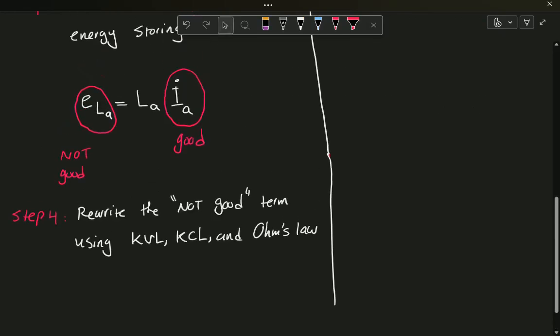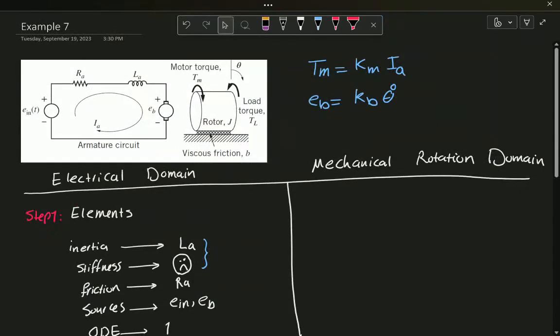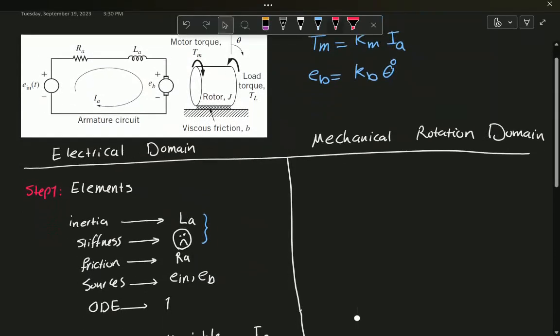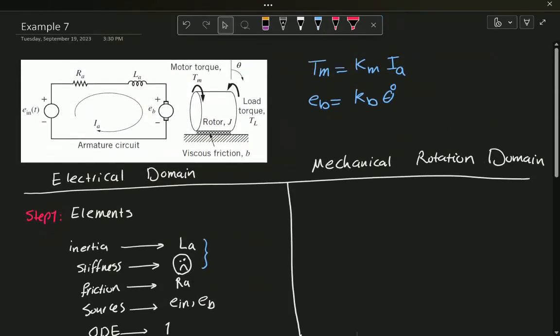Okay, so look at this. What are my options? Can I write down KCL for this problem? Well, I need a node. I do not have a node in the circuit. But however, I can write down a KVL. Okay, so let's go ahead and walk on this circuit in the direction that I showed. Convention 1 says that because I'm moving in the same direction of the current, the voltage across the resistor and the inductor drops.